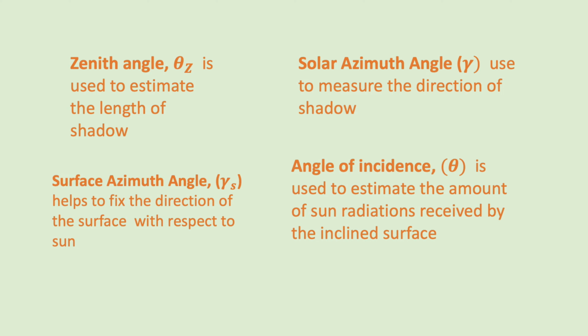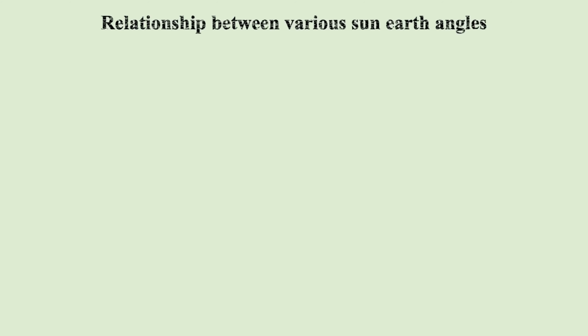This is the kind of input we are giving to the solar devices, and on the basis of the input we can calculate the performance by knowing the output from the installed devices. The angle of incidence theta is the angle between the incident solar beam fluxes, and this angle is a function of latitude, declination, tilt angle, azimuth angle and the R angle.